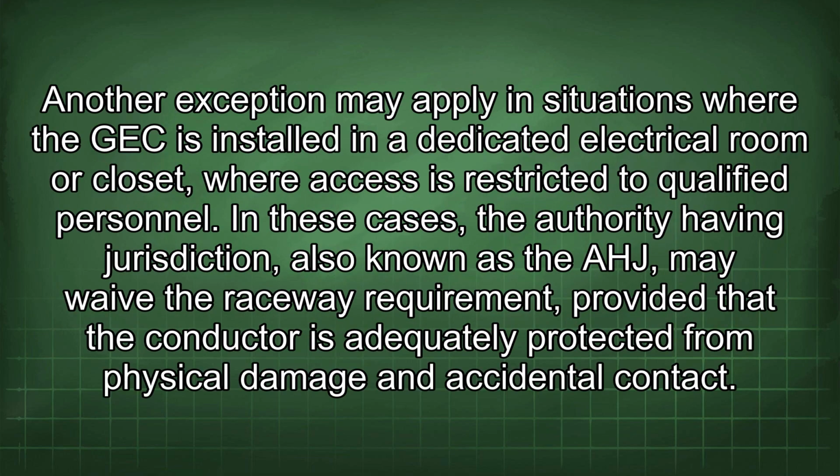Another exception may apply in situations where the GEC is installed in a dedicated electrical room or closet, where access is restricted to qualified personnel. In these cases, the authority having jurisdiction, also known as the AHJ, may waive the raceway requirement, provided that the conductor is adequately protected from physical damage and accidental contact.